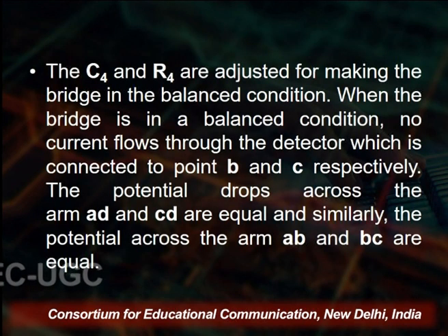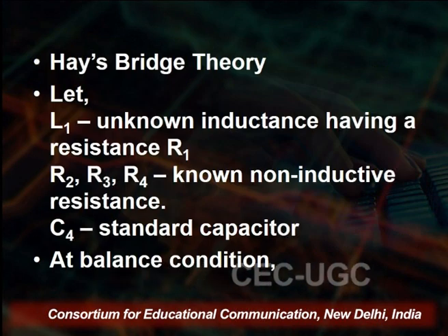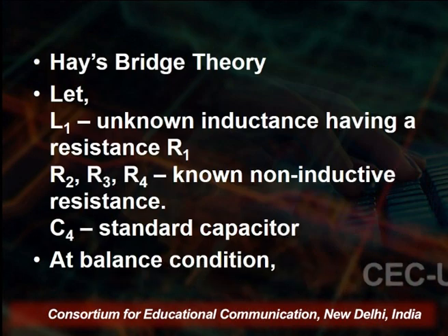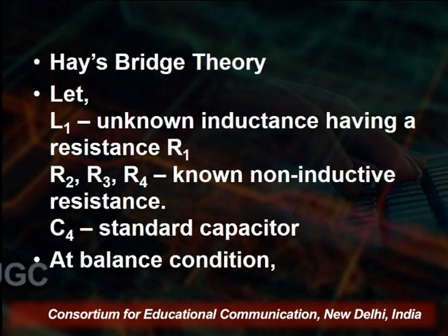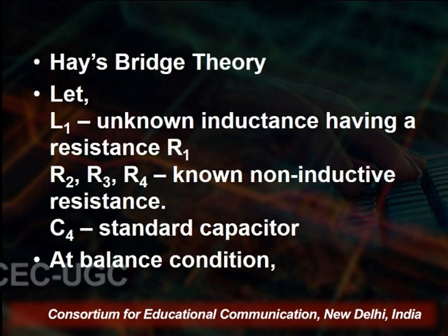So by using this, L1 is the unknown inductance having the resistance R1, and R2, R3 and R4 are the known non-inductive resistances, and C4 is the standard capacitor.